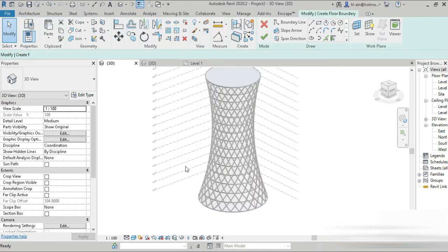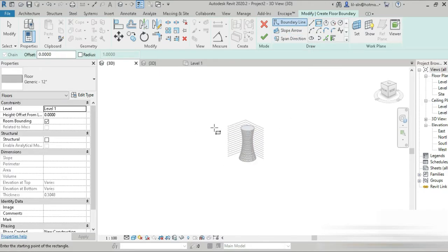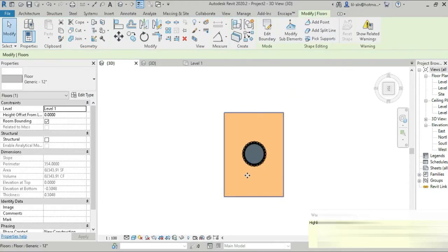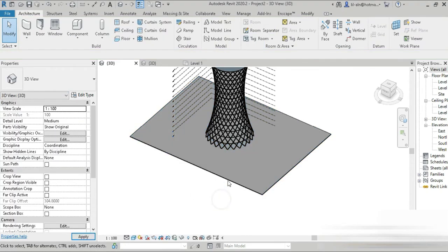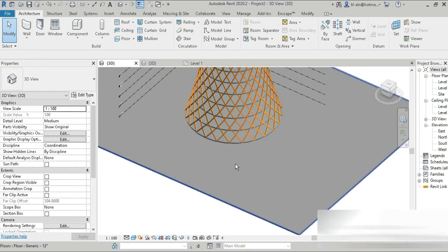If we go to floors from here and level 1, rectangle, and let's go to the top, and let's make this so highlighted floors overlap, no problem. We can minus 12 inches, and it wouldn't overlap anymore because the thickness of that is 12. So how about minus 12? Why can't I type minus, right? Minus 12 inches, and now it's not going to overlap. Okay, so it went down. So the overlapping problem is finished.